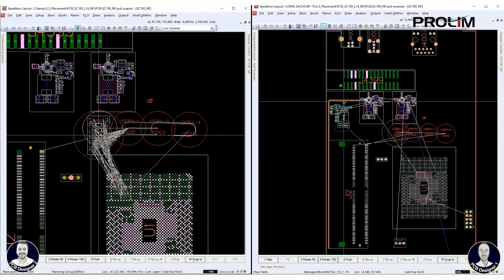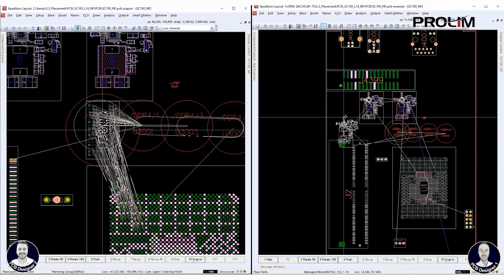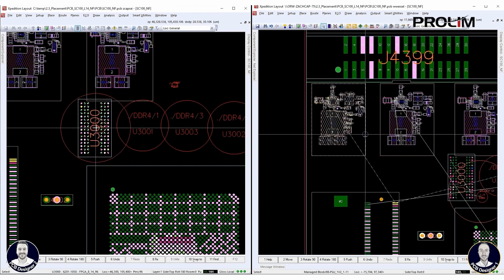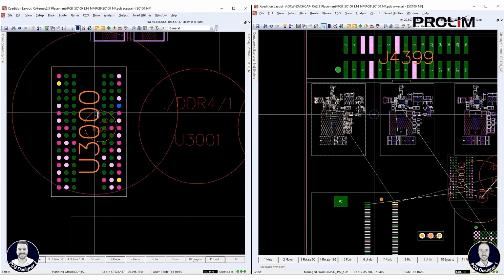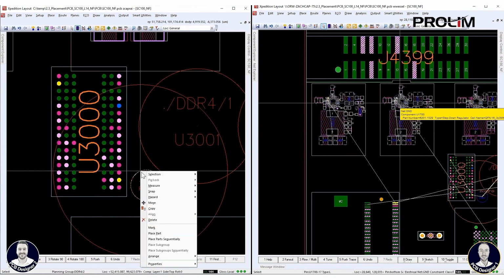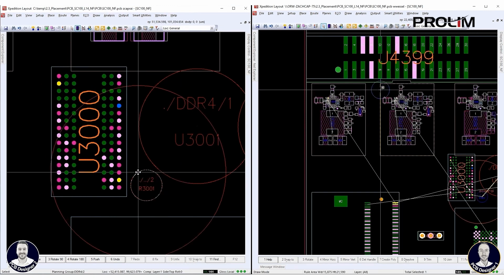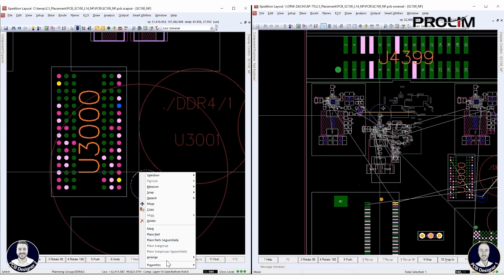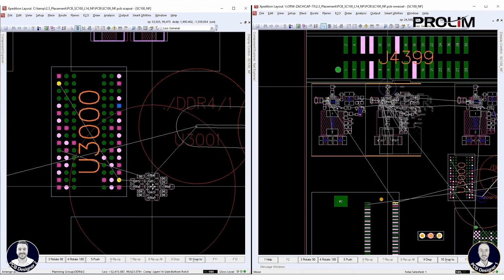Component groups still show the user netline connectivity between themselves and other components, which can help in determining the best place or location for groups of components. They also are sized based on the size of components within them to help determine the board real estate that each group may take up or occupy.